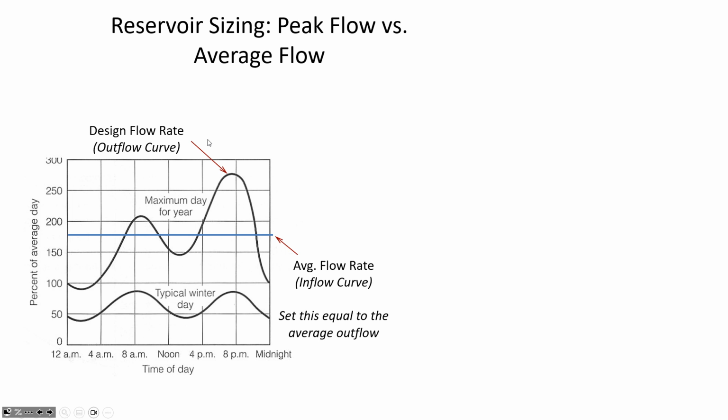It's falling down, right. So what we want to do is make the reservoir big enough that at the worst, the water level almost is empty, but then it starts to fill again. So it's fluctuating through the day, but it never gets empty. We don't want to make the reservoir super big because then there would be a lot of leftover water that didn't get consumed. But we want to make it just barely big enough.